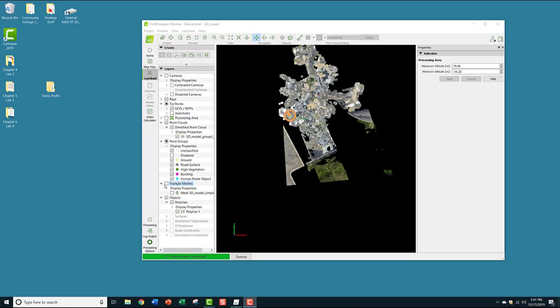Now, the purpose of this lab was to develop the highest quality 3D textured mesh. Since a 3DM is a derivative of DPC, we needed to perform an advanced manual classification technique known as image annotation. Lastly, we constrained the image to the project with the processing area. Now, it is advised that image annotation be used in combination with other manual classification tools discussed in the previous chapter to develop the best DPC possible. Consequently, the latter will yield the best 3D model.